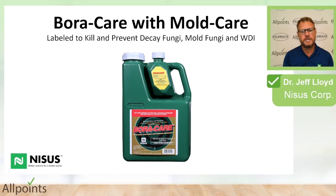Now, if you do want full protection against subterranean termites as well as the other wood destroying organisms and the surface fungi or mold fungi, then do carry out a Boracare application at a 1+1 dilution. The Boracare with Mold Care is designed as a 1+5 dilution. So one of these co-pack units here is mixed with 5 gallons of water for application. And just incidentally, 1 mixed gallon will treat up to 400 square feet of surface area. So it's really quite a cost-effective treatment to do. It's quite a nice dilution that you have there with this professional concentrate.